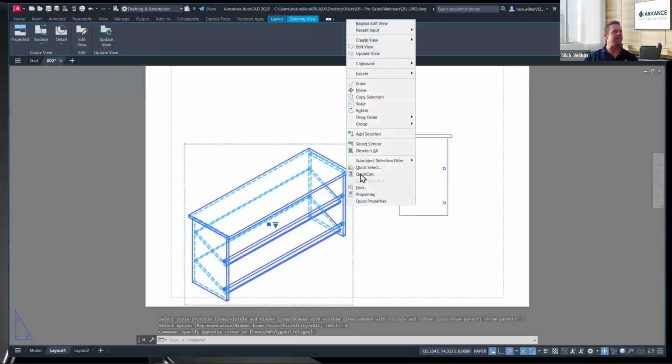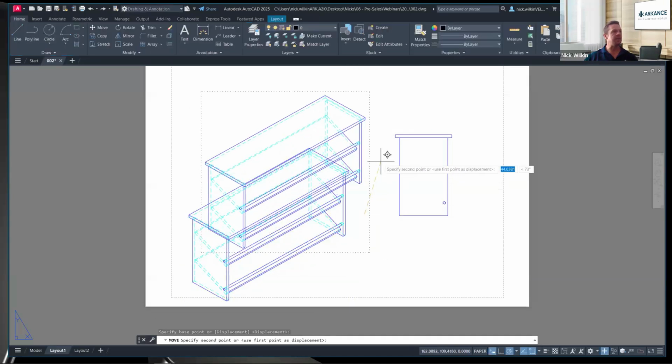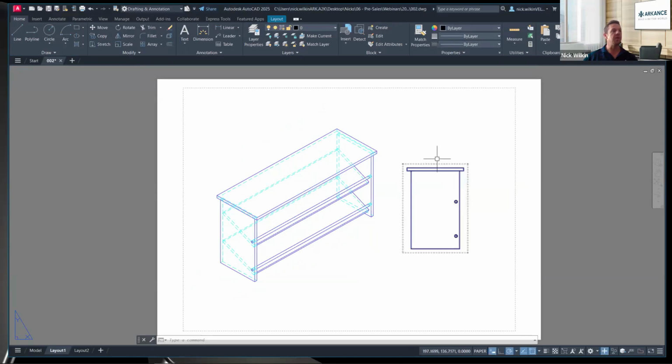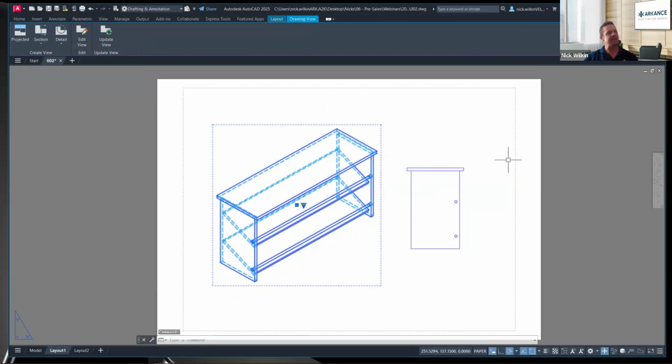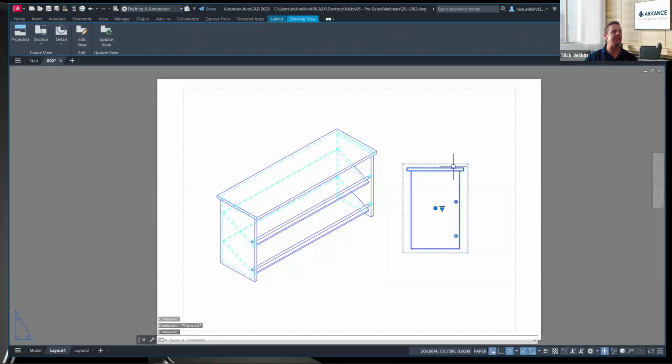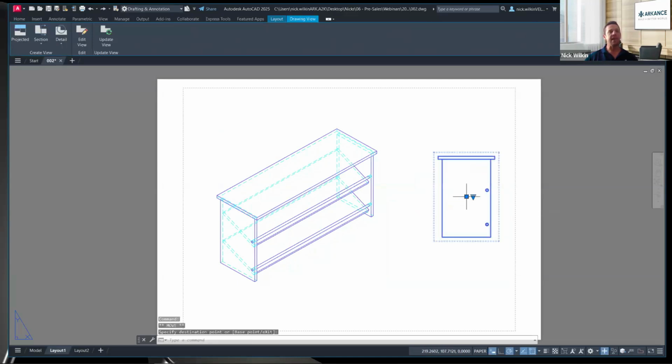All right, now the one thing about this, and I will have to get my Inventor going for this. The one thing about this is that when you do changes, and this is just a tips and tricks for you, you would think that this is live, and it should be live. So this should update automatically because that view is directly linked from the view in Inventor, right? But what you might not know is that this view is linked to the IPT. Any of the Inventor users out there will know that that means it's a project, right? So it's linked to the project.